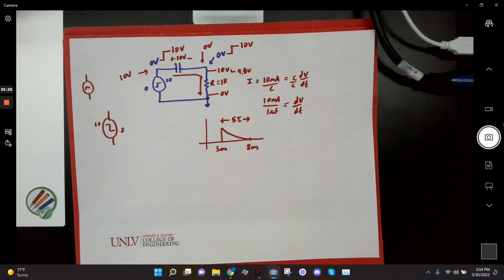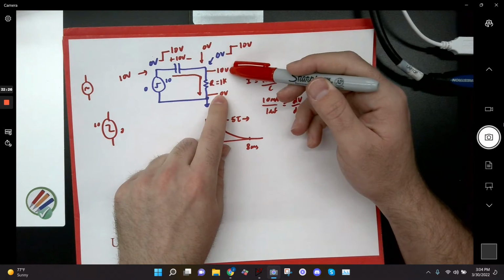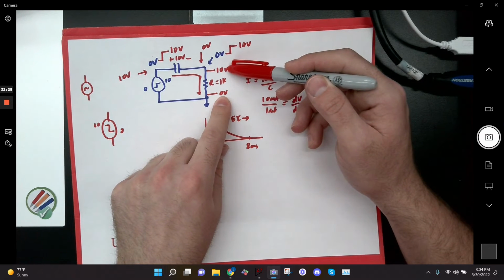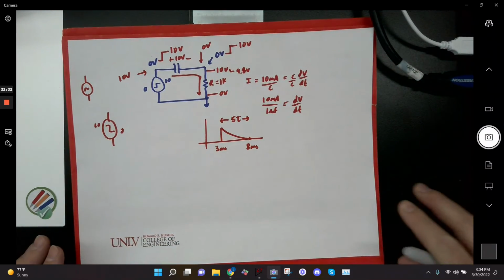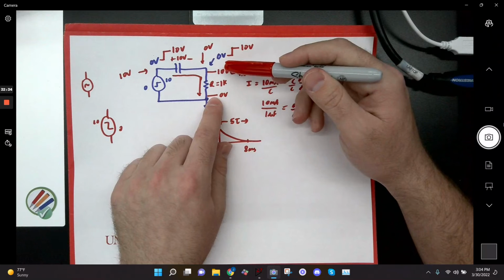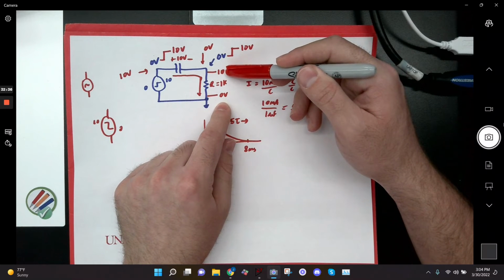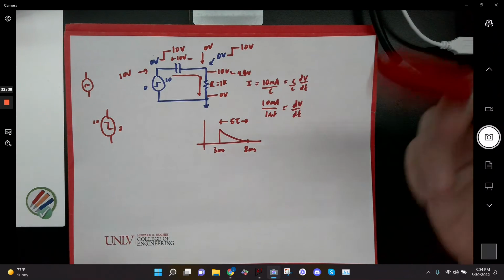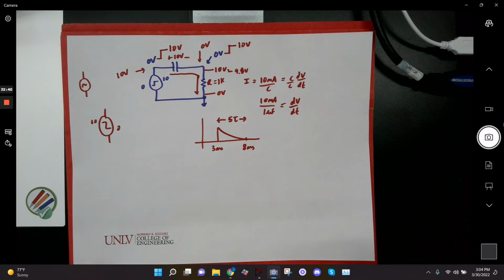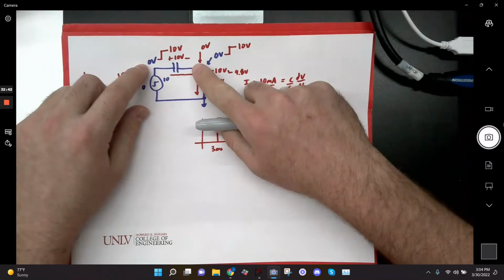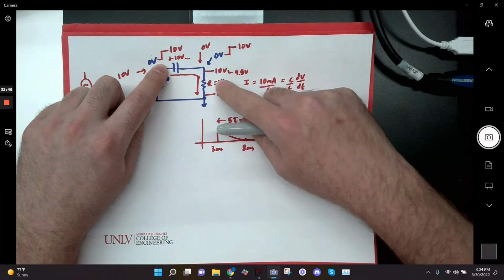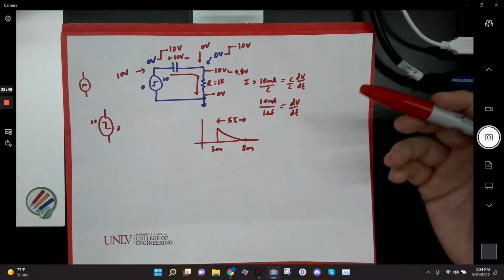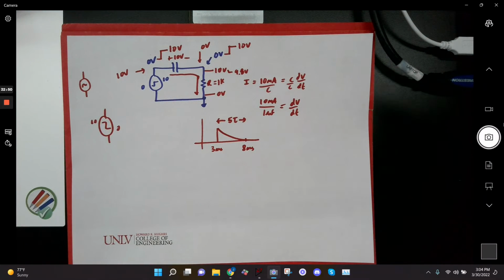Okay. Cool. But I would say it's probably better to think of what's happening with the actual resistor, because I don't know that that's actually what's happening physically. What is actually happening is that if I have a voltage difference across my resistor, Ohm's law kicks in and I get current flow. Then as my capacitor starts to charge, the capacitor voltage has to go up, which means this node has to go down, and then that current gets lesser and lesser until there's 0 current flowing in the circuit again.